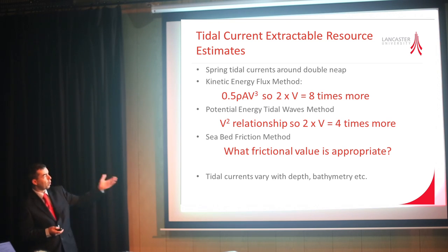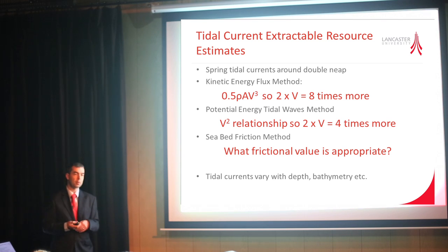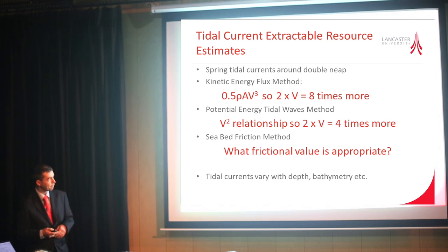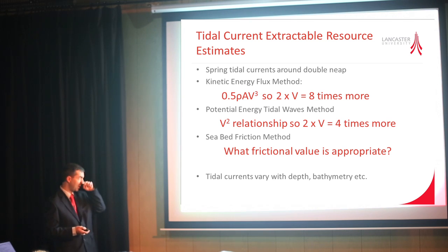But what friction factor do you use? It depends what the seabed is, whether you've got weeds, whether you've got debris, whether you've got rock faces. All sorts of factors could go into that particular calculation. So what I think is important is that for any potential location for the type of technologies that we're looking at, you need to make sure that an appropriate site survey is done beforehand, so you understand the tidal flow, you understand the conditions, and you therefore get a realistic estimate of the potential power capture available.